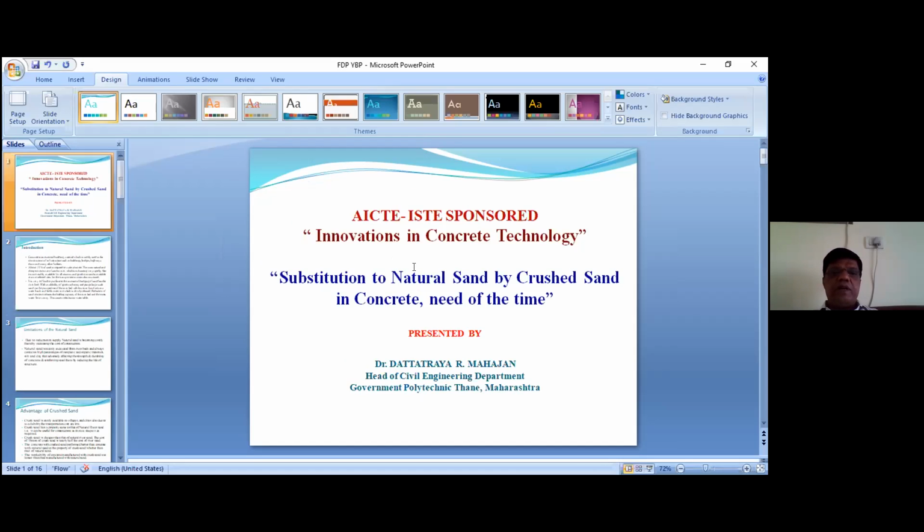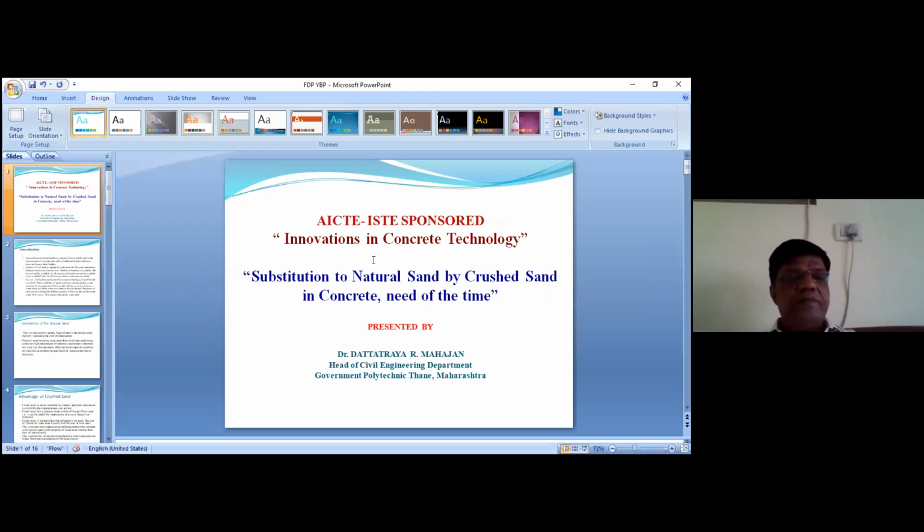So what is the alternative? I suggested he use crushed sand, and there was only one supplier in the district. Fortunately, it was there, because previously it was not. They gave us the mix design for M30 and M35. So we took 4 to 5 trials and gave them a good mix design, which worked wonderfully, and they were able to complete their remaining work within the stipulated time using the crushed sand.